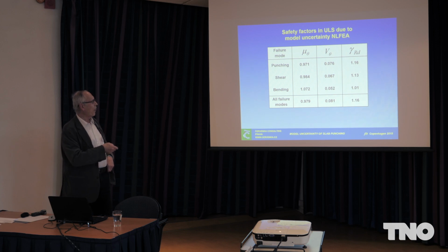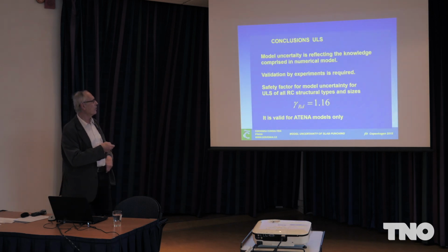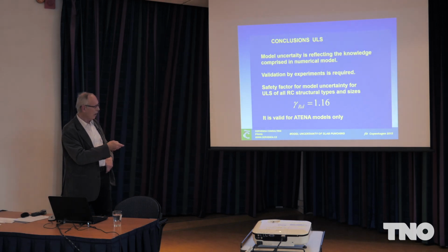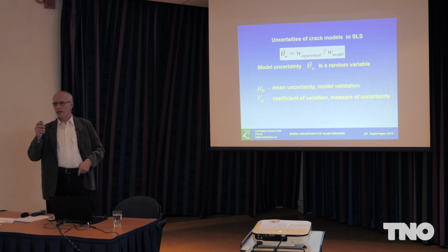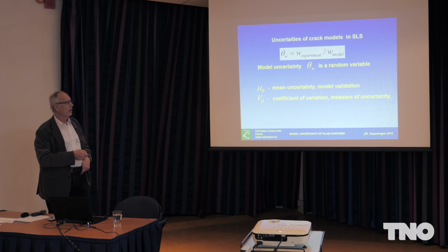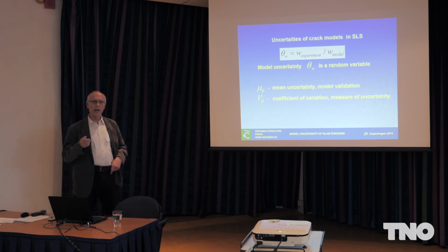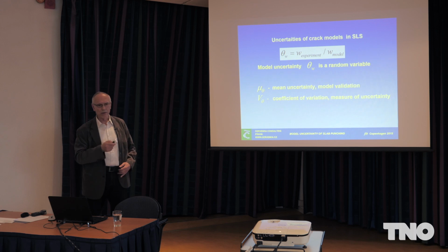So this is closing the part related to ultimate limit state strengths, and I will show you very briefly a few examples. I have already said this, and very briefly, another consideration, another study for serviceability states. So we say, okay, we are trying to investigate relation between modeling crack width and experimental crack width. And this is model uncertainty, and it is for crack width only.